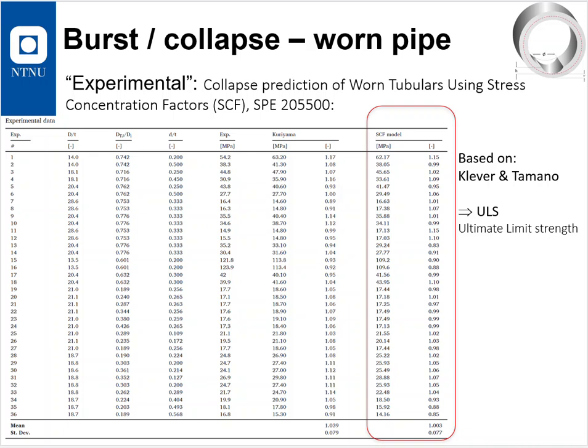Now, what is interesting, I think, is that elastic collapse is fully mathematically developed. It's not correct to say collapse, like I said before. It's an instability calculation, buckling, whereas yield strength collapse is also a mathematically derived calculation, both of them very accurate whether you use API or not.